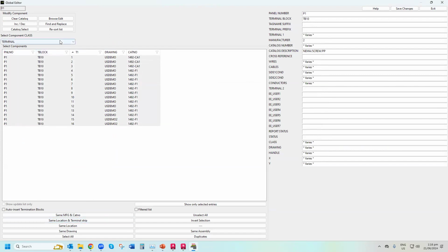So I quickly go through this, point out a few other things: wires, cables, miscellaneous. Anyone else's text or attributes will appear in that little section there. Title block, as the name implies, is pretty understandable. Extra parts: you might not only have to buy a relay for a panel, but you've got to buy a mounting plinth to screw it into the panel with. So these are things that you want to factor into your cost but don't need to be seen on the drawing.